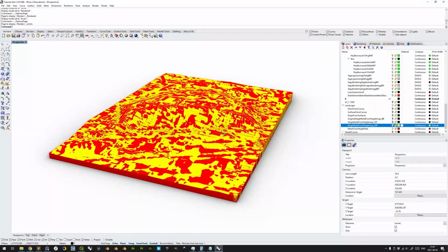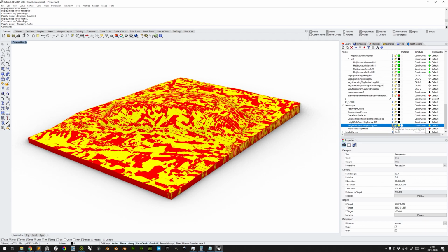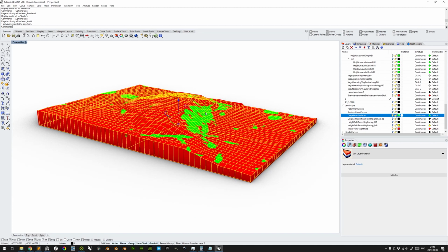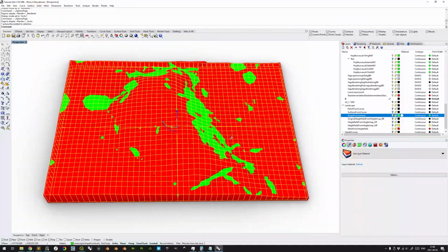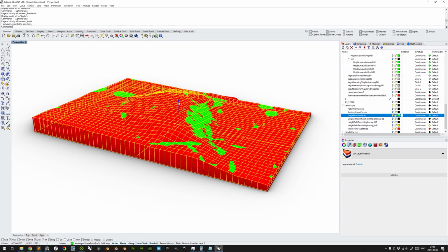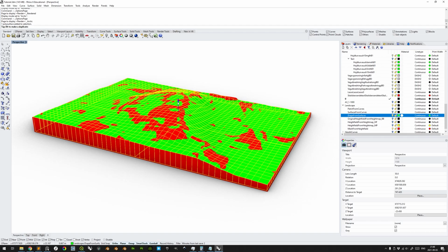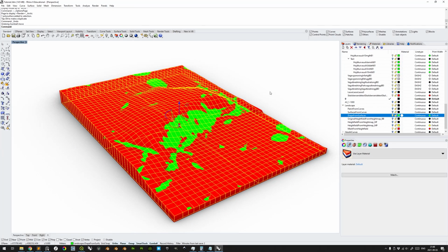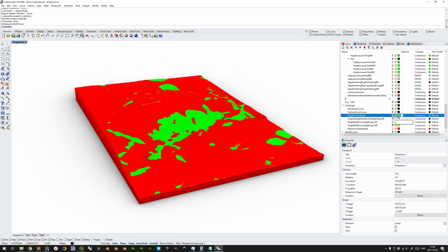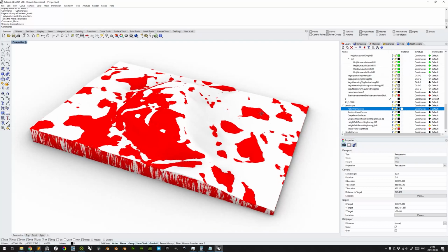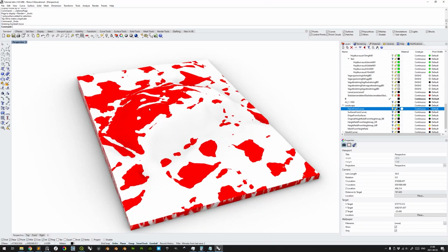Here you can see that the overlap between these is very similar. Keep on using the mesh here to see if we use the drape here. We can see that the drape is generally lower, but for the curve, for the most steep parts, it actually protrudes upwards. But we can see here that moving half a meter upwards makes them comparable, but not identical in any case. I'll undo that. I'll hide the drape here, and then we can show the patch, and we see that the patch is actually quite similar for some areas, but definitely not all.